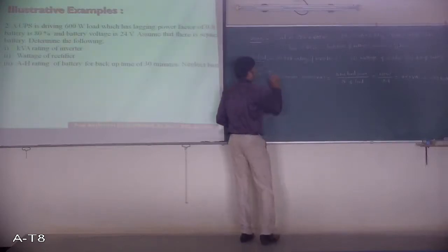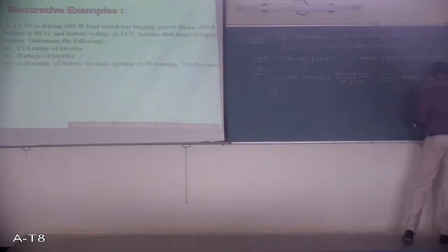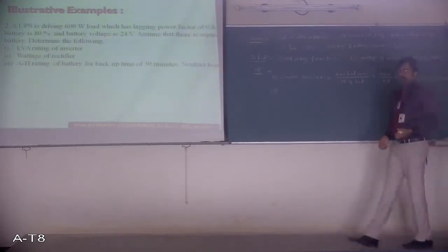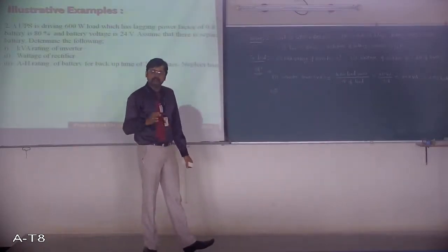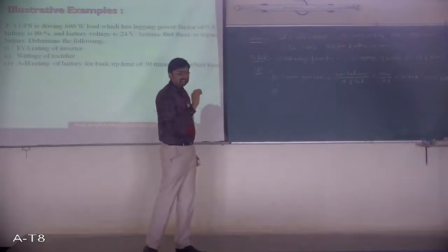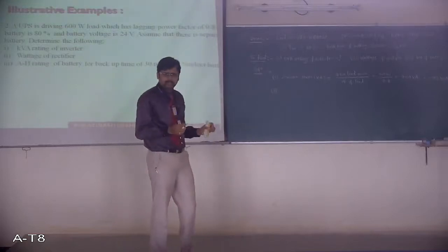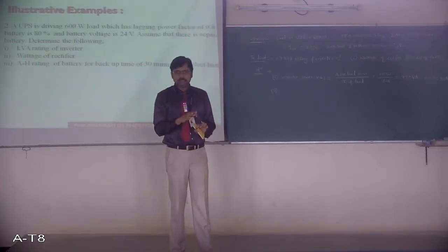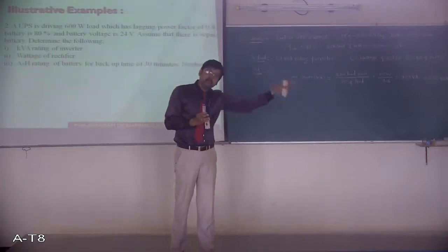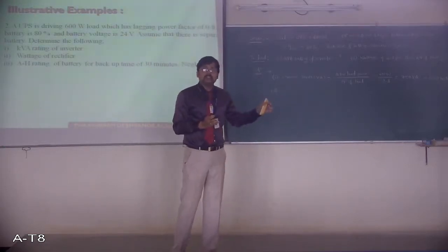Now let us determine the wattage of the rectifier. How do you calculate the wattage of the rectifier? A similar thing we have already calculated in problem number 1. Some clues are there that you can learn from problem number 1, and you can take those clues to solve this. Remember, your rectifier unit is behind the inverter. So the rectifier has to supply the load power as well as the losses in the inverter.